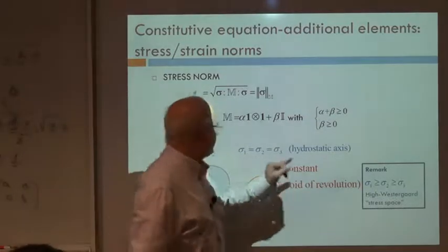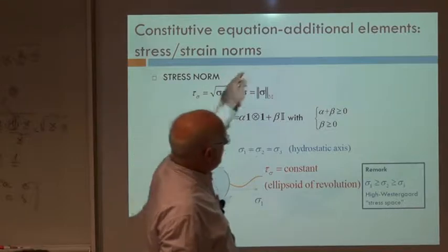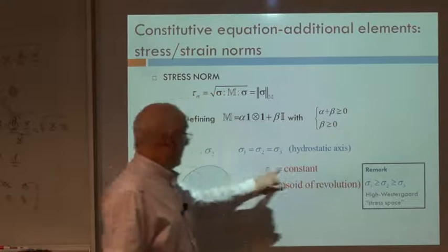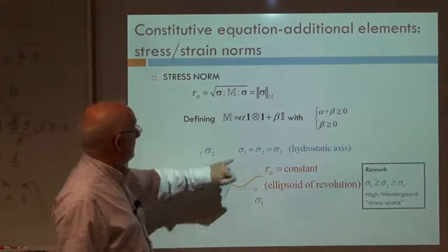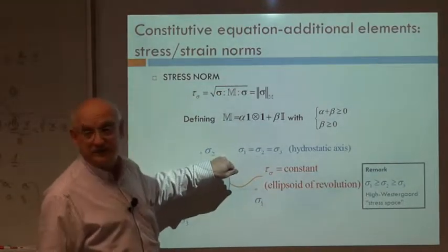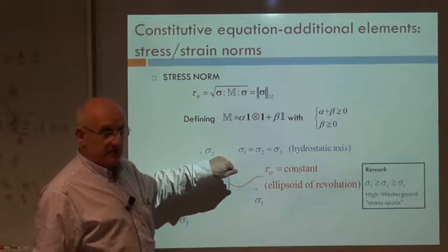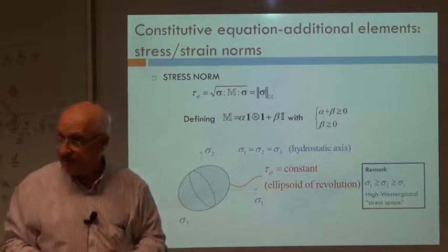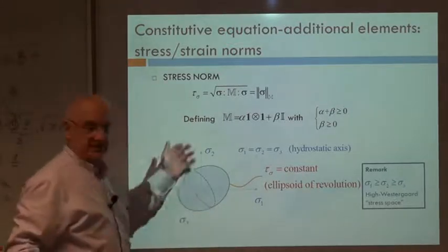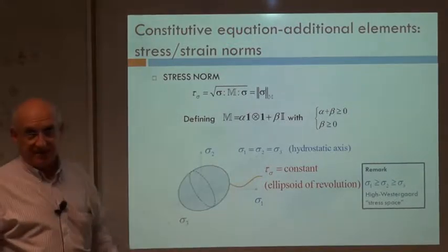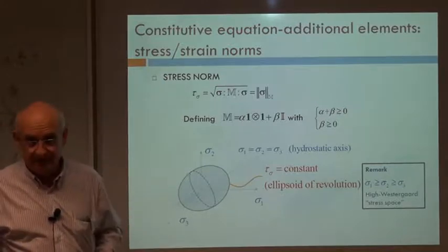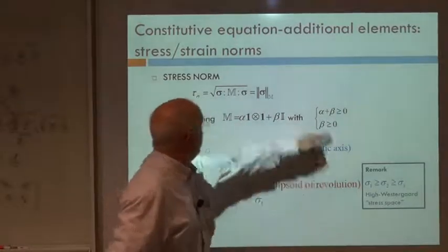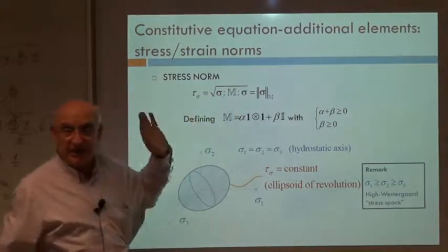And then this stress state, which is characterized by the 3 principal stresses, corresponds to one point in this space. So finally, if I consider all possible stress states, I would fill this space of points, every one giving the 3 principal stresses corresponding to the stress state I consider.